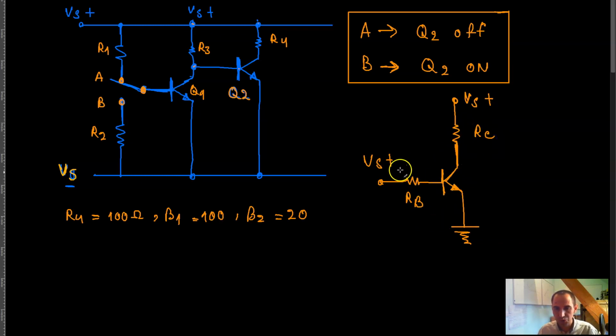And then of course you choose this resistor in such a way that enough current flows here so that the transistor is set to be turned on, right? We have talked about this before, so I don't have to go over this over and over again. So that means that you have to start from here and then choose each and every one of these resistors in such a way that this acts as the base resistor for the transistor Q2, right? That's basically what you would do.